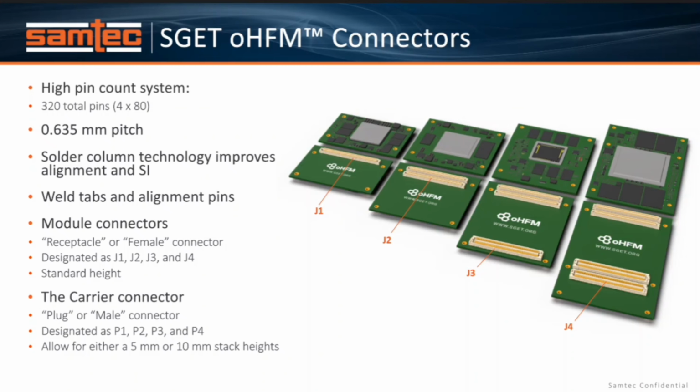Because these FPGA-based SOMs are sometimes going to be used in mil aero, industrial, or other rugged applications, we wanted to make sure that we had ruggedization features. So each connector, both the receptacle and the plug, has weld tabs and alignment pins. We'll talk about that in detail.